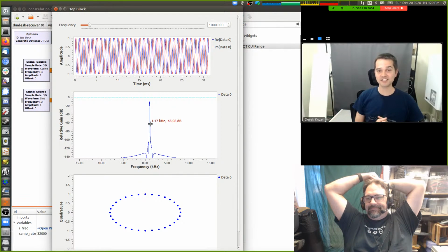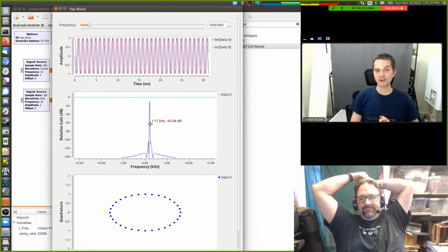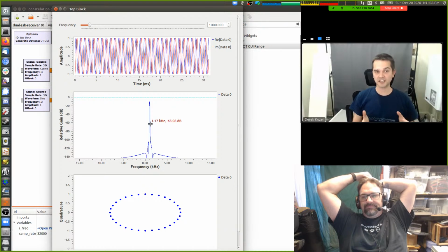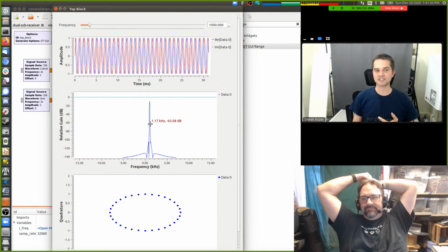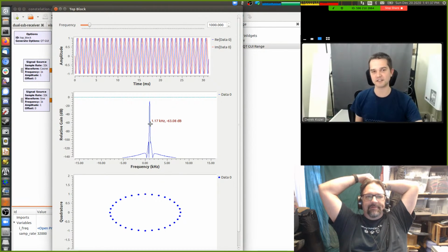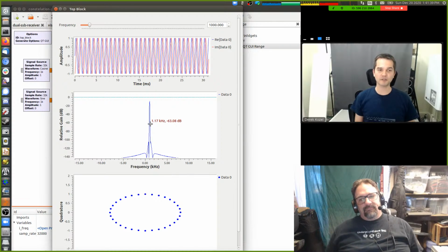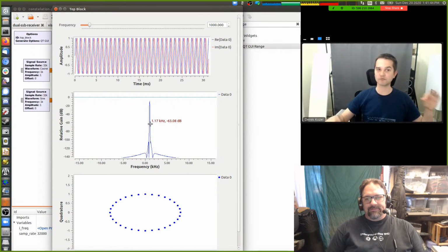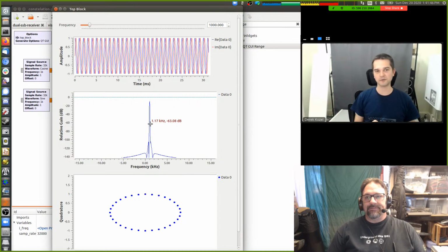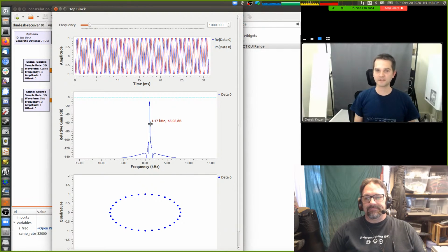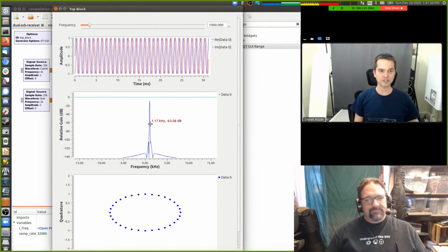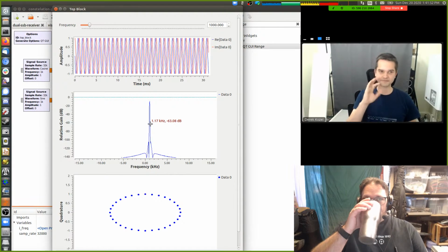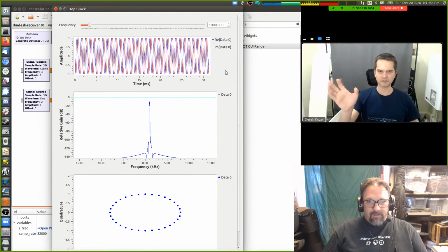The issue is that we aren't using locking, in the programming sense, to set both of the frequencies at exactly the same moment. If one of the blocks is running as you're setting it, or runs in between setting the two, you'll get a phase slip between them, which sucks. There are ways we could go around this, but this will work for our purposes.